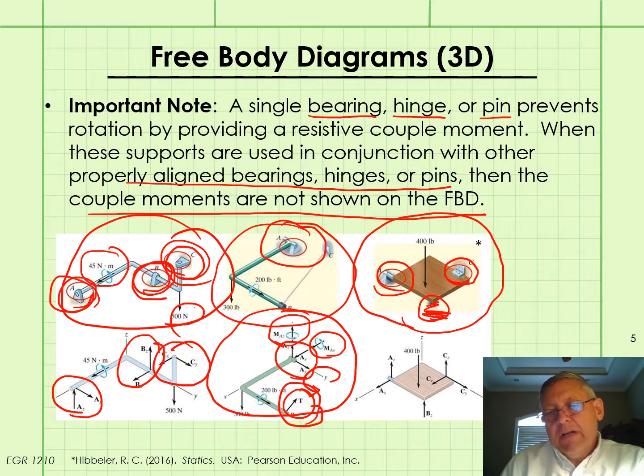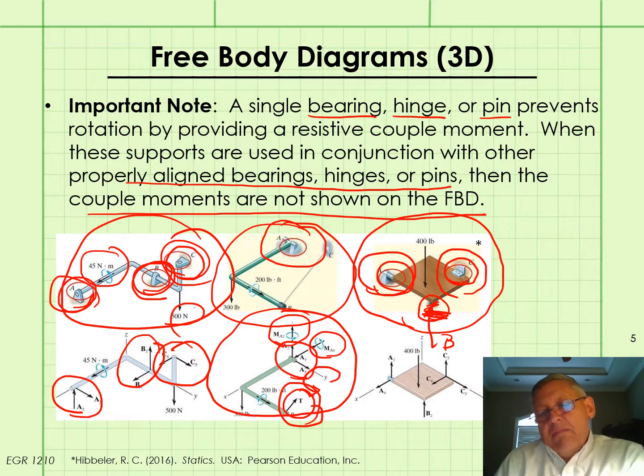But that roller bearing is there, and so now there's a force being provided by the roller bearing at B. And given that situation, hopefully you can see that there are no moments being created by the reactions at the supports at C and A. So it's a case-by-case thing when you can ignore the moments and when you can't.